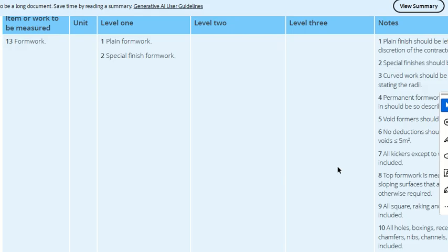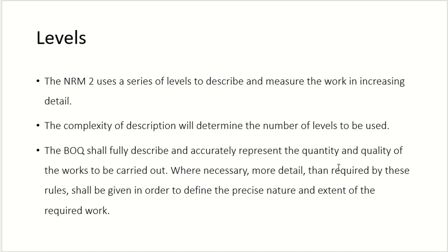So if I am giving the price of concrete, I should give you the price of form work as well, according to the standards. If you are taking the price of concrete only and you are not asking for the price of form work, or he is not giving the price of form work, that means you are missing one item. Got my point? So this is where the NRM can be helpful. I told you, you can even see the activities which you need in your BOQ. So this is another method of using the NRM.